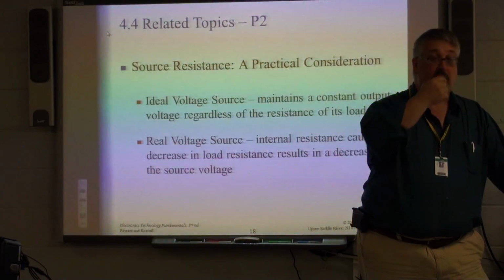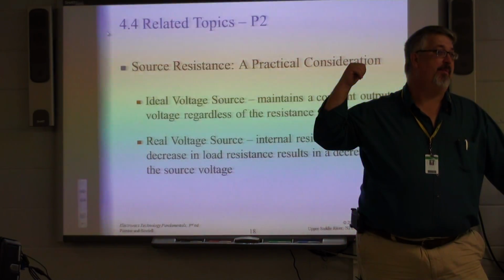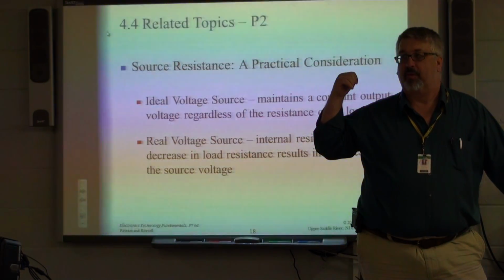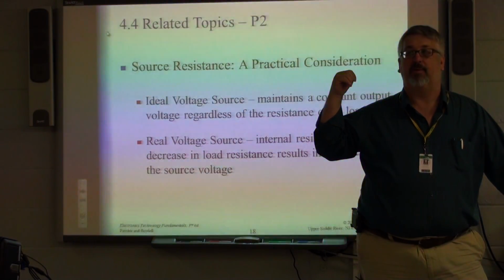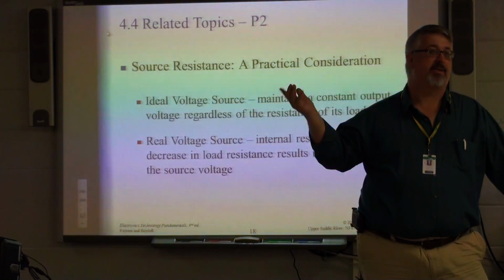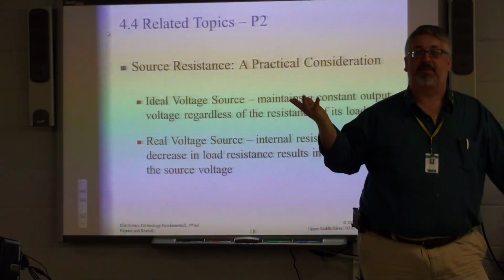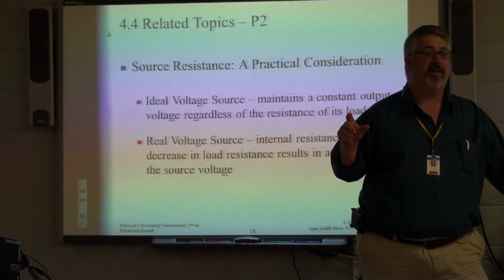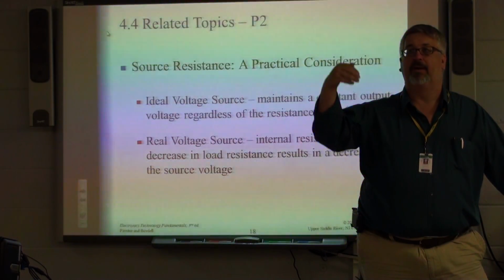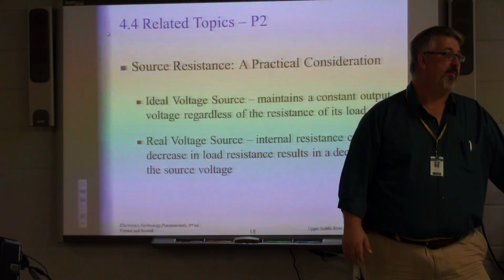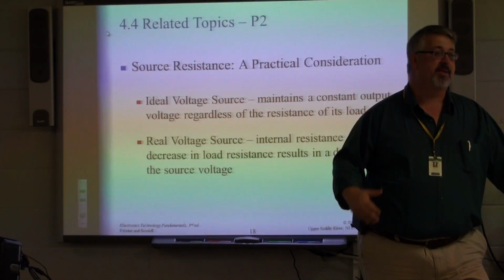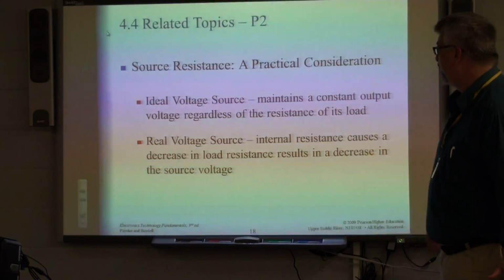You take that 9-volt battery back there that's brand new, and this guy mentioned it in the measuring video yesterday when he was measuring batteries. We measure 9.1, 9.2, we may measure 1.6 on a 1.5 volt cell. That's because it's not under load. When we put it under load, it drops down to more like the 9-volt range for a 9-volt battery, 1.5 volt range for a 1.5 volt battery. And that's just because there are some drops associated with applying a load.